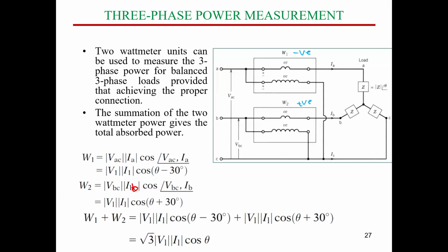Why? Again, can you see here, guys? So wattmeter 2 here is connected to measure phase B current. So this is the current coil, and the voltage coil is connected between B and C. You know that if I have A, B, C, so B and C is positive, A and B is positive, C and A is positive. So if I measure AB or BC or CA, this is positive sequence. So the second wattmeter here, W2, is measuring BC volt. So this is the positive sequence wattmeter.